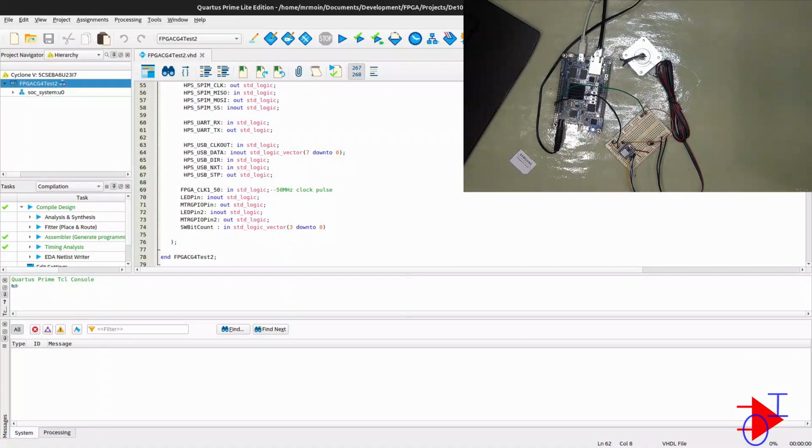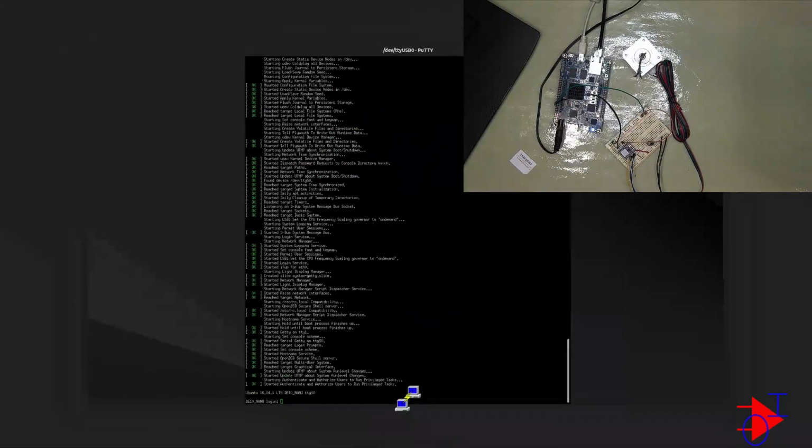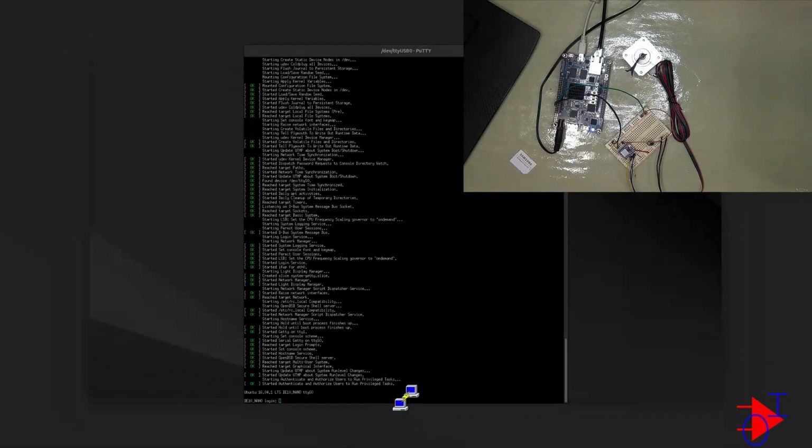So let's close our Quartus. We don't need this anymore, at least for the read portion. We'll come back to this when we want to write from the FPGA, which is going to be a similar process. Instead of output, we will say input, and then we will have to decide the width of the number of bits that we need to occupy in the write sequence. And then similarly, we'll modify the read portion in the HPS.